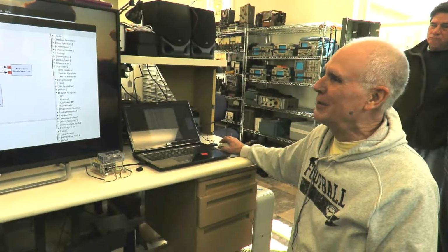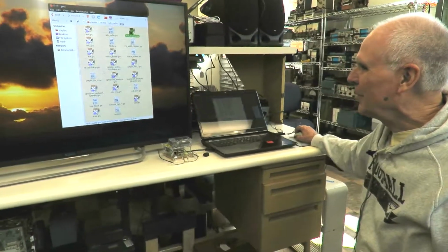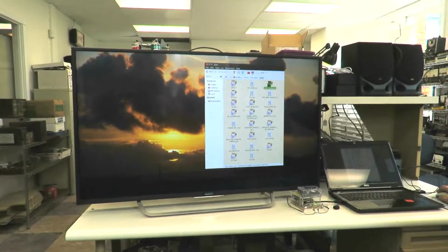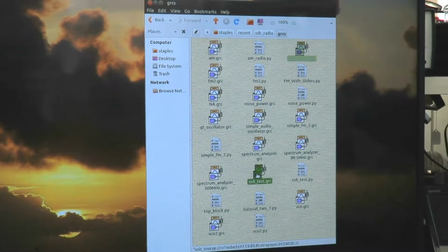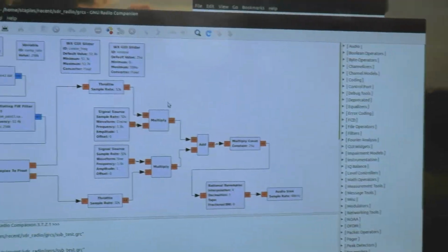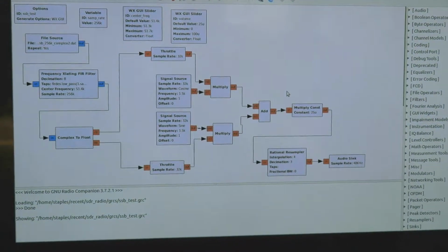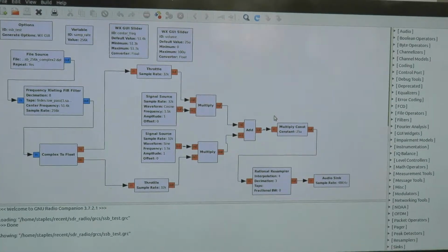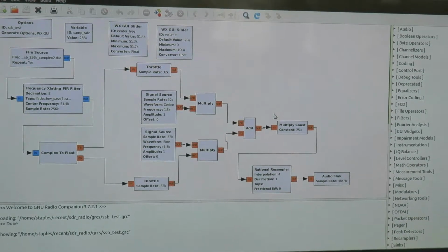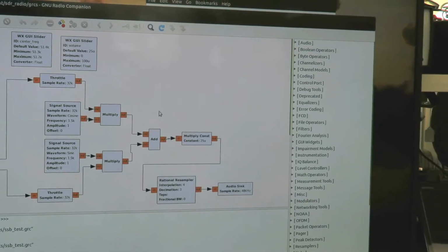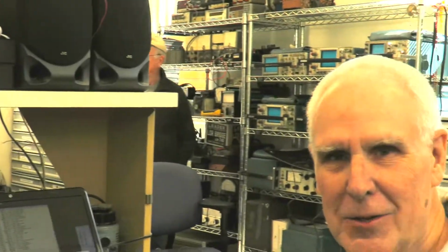But there's a whole lot of other things that this thing can do, which is kind of amazing. There's a number of receivers in here. One of them I didn't write; I wrote the audio sweep generator. But here's an interesting one, which is a single sideband receiver using the so-called third method. Does anybody remember what the third method, also called the Weaver method of single sideband generation, is? You actually insert your carrier right in the middle of the audio, about 1.5 kilohertz. And if you do it in quadrature, at 0 to 90 degrees, you can actually get a single sideband signal.